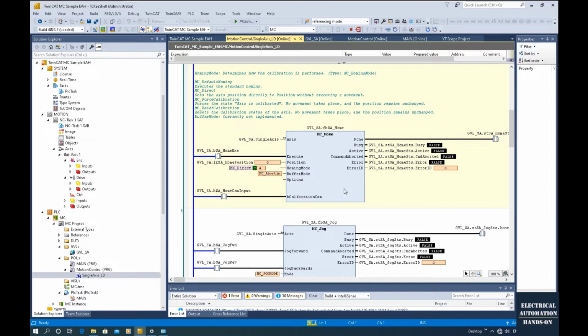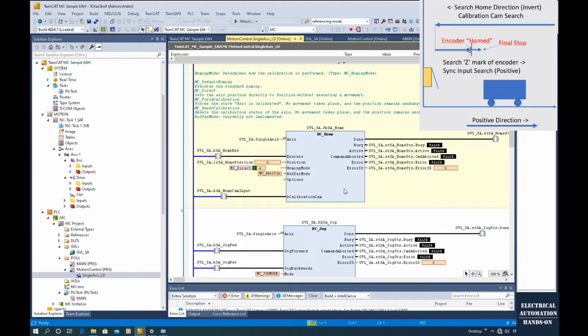After we shut down the power, recycle power of the machine, the incremental encoder will lose the value. Basically, the value will be zero. But maybe your tooling or your motion system is stopped at some place, maybe 100 millimeter or some other value, which is not a zero position or some defined position. So after the power cycle, after the incremental encoder lost the value, we do need a sequence to allow this system to find the home position.